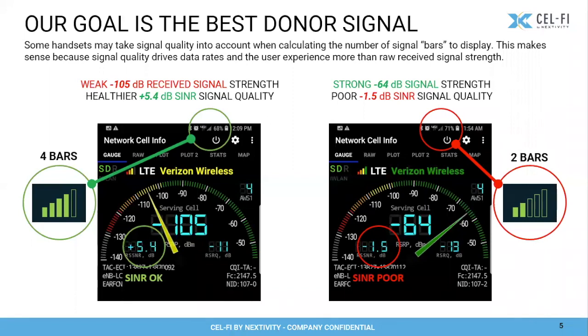But if you take a look at the picture on the right, it's still my phone, but it's only showing 2 bars. Now, this signal is very, very strong at an RSRP level of -64, but the signal to noise ratio is -1.5. Right? So even though it has a much stronger signal, it's showing fewer bars.